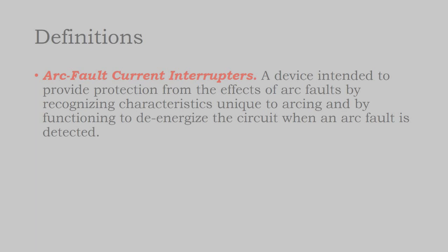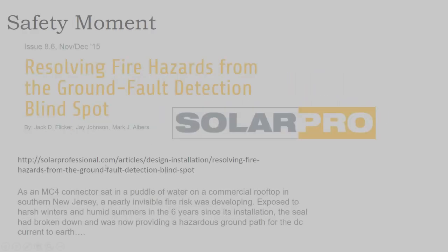And that's produced kind of a phenomenon where owners of older systems think that solar arrays are bulletproof and nothing ever goes wrong with them, whereas you install a newer inverter with the arc fault detection and it recognizes when that MC4 connector is not made up correctly but still operational, and it shuts off. So that's for the best, but it's also showing you that older legacy components eventually should be upgraded to the latest iteration of code.